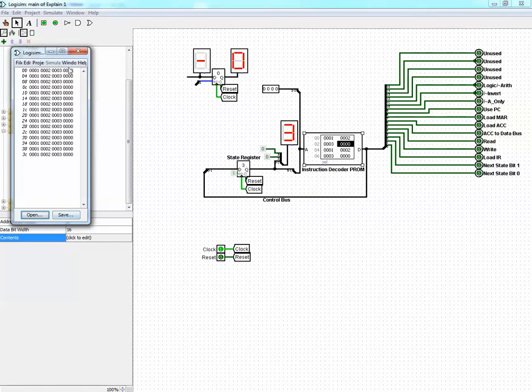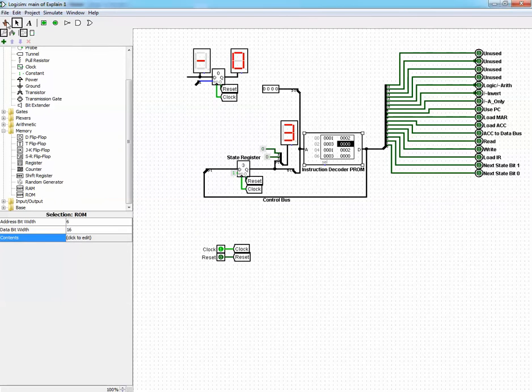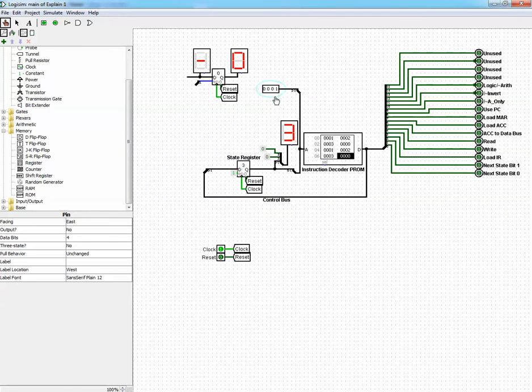That corresponds to this 0, and this is telling us to reset back. But instead of resetting to this value, we want to reset to that value. So in order to reset to that value, you need to toggle this keypad, which is the least significant bit of this pad, which is basically bit number 2. So here is 0, 1, and bit number 2, which corresponds to 4. And then let's toggle.